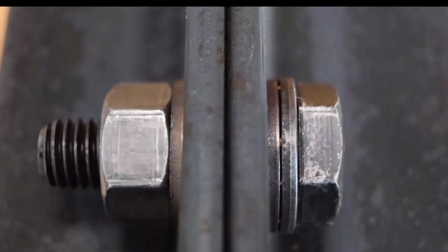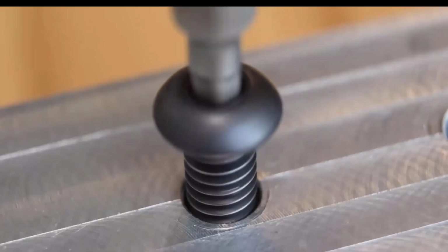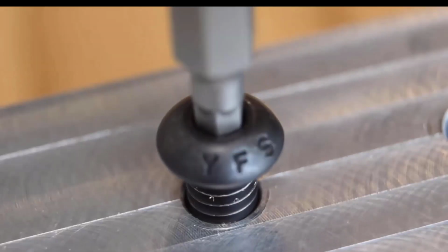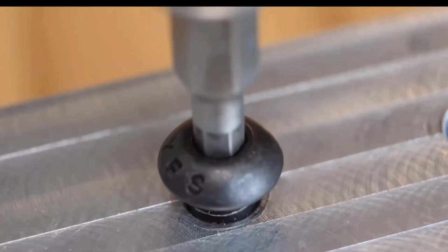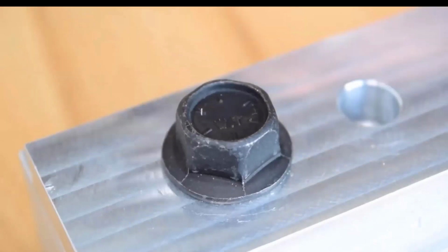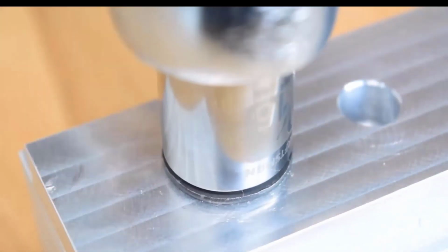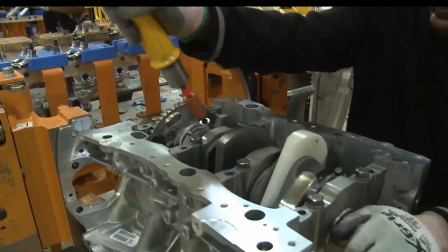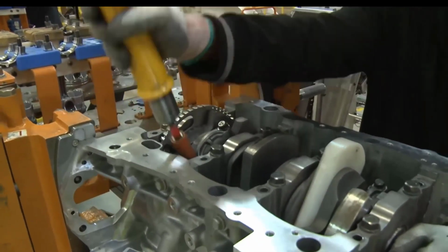It's generally best practice to use a washer under the head of a hex head screw as well as the nut. Washers are not often used on socket head cap screws, but to get away with this, it's important to specify a close fit on the clearance hole. An alternative to a free washer is a flanged screw or nut. These are preferred on mass-produced products to eliminate the handling time of a separate washer.